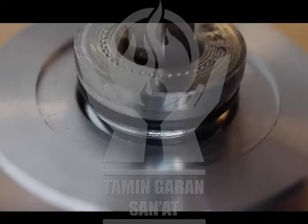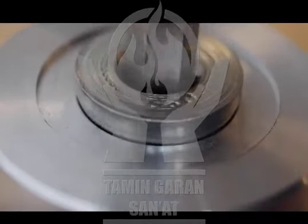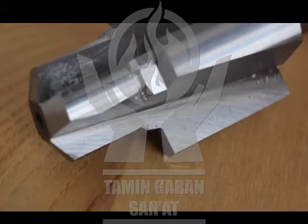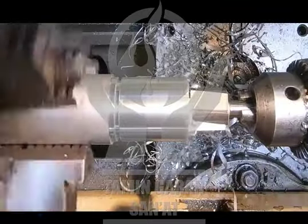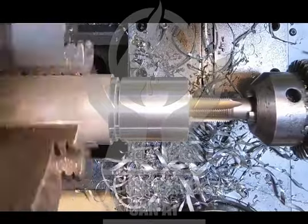A third type of design is a boss seal. You pretty much only see them on hydraulic fittings, but they have a lot of advantages for other applications. In this configuration, the O-ring sits in a triangular space that is usually made with a special form tool. Boss seals are really easy to manufacture since there aren't any undercuts, and if the gland gets damaged, they can be reworked just by machining the profile slightly deeper.